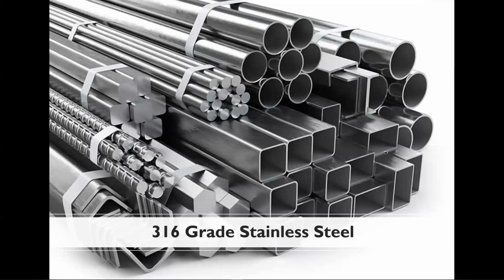But this is an ongoing study and research as of today, due to the complex modeling required to simulate each of these material characteristics. So overall, additively manufactured 316 stainless steel is a viable material, given its anti-corrosive properties and inherent toughness for biomedical applications, as well as other applications throughout industries.